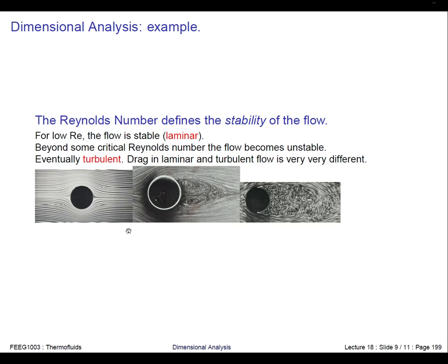So you can change the Reynolds number in different ways, but as long as you change it to the same value each time, you'll get the same flow patterns behind it. This is the key thing to think about when you want to go from a model to a real scale and back again. If you can keep the Reynolds number the same, you'll get the same physics. And this is how you can go from real scale to model scale in the lab.